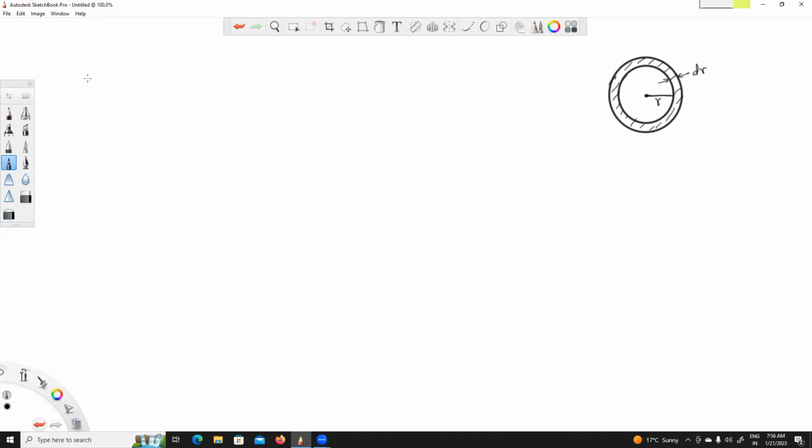Now we have this shearing stress. Let me write this shearing stress. This shearing stress, denoted by tau, is equal to G theta upon L times r. Now we'll find the twisting moment. This shearing stress is produced basically due to a tangential force, right? So how to find this tangential force? This tangential force would be given by F equals tau times small area dA.